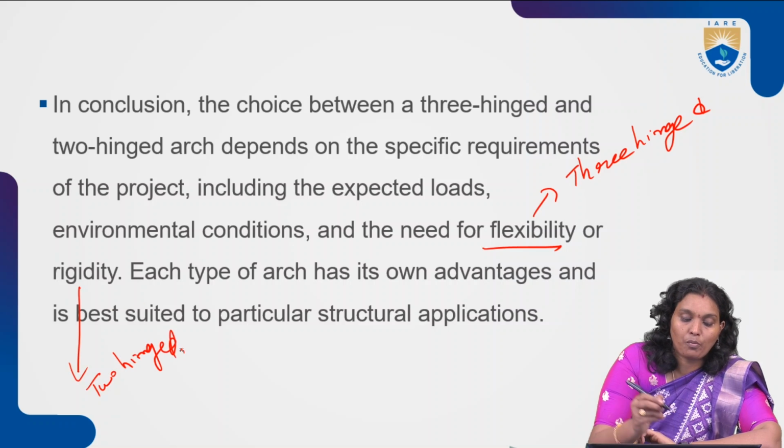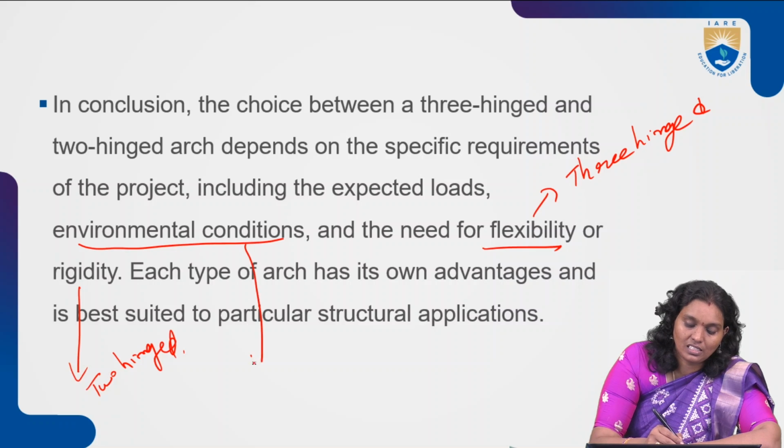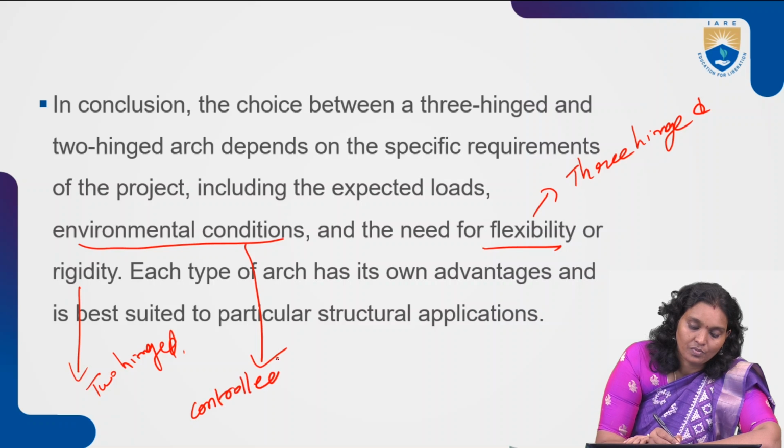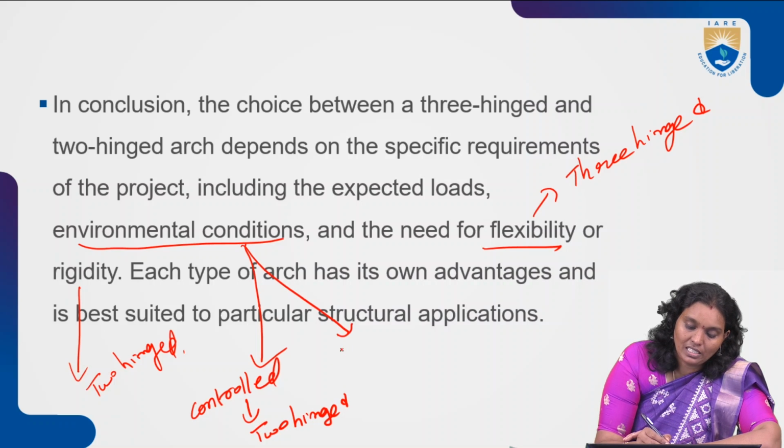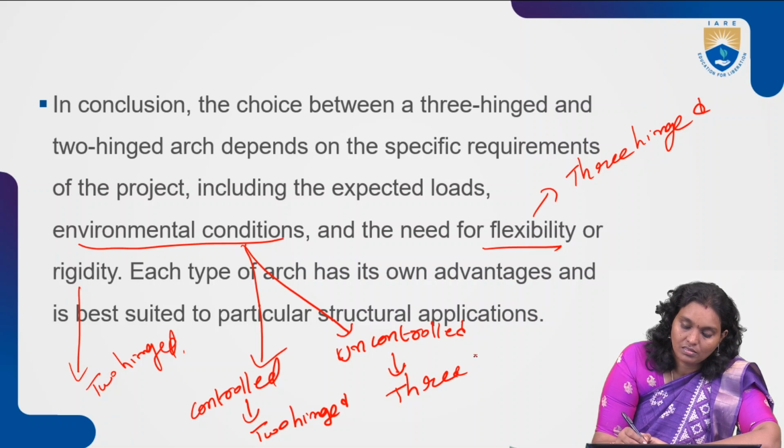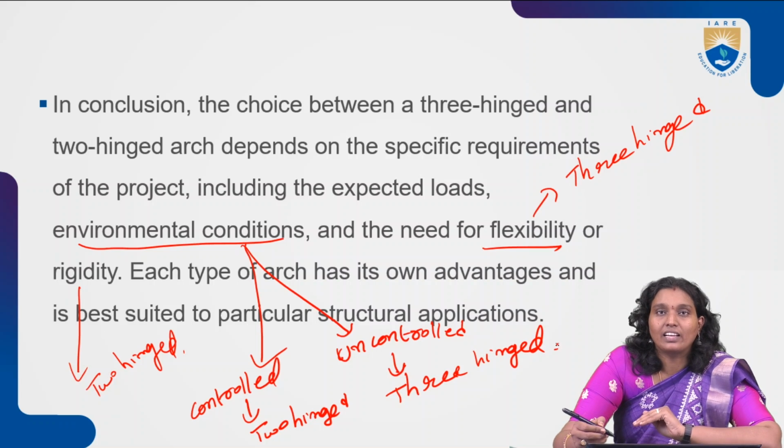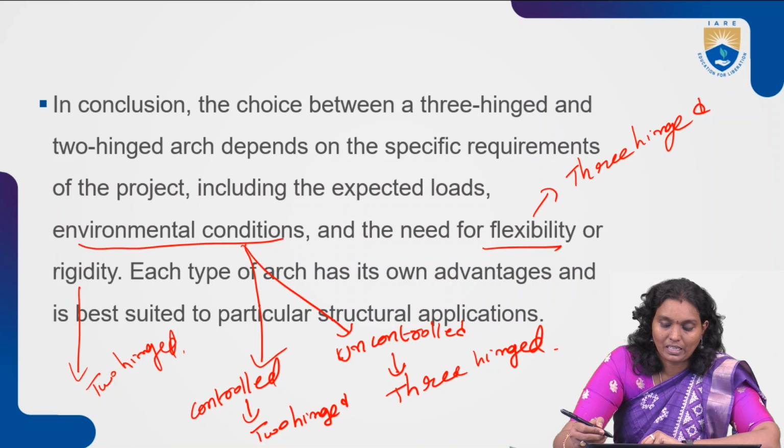From the environmental point of view, for controlled environmental conditions and temperature effects, the two-hinged arch is adaptable. Under uncontrolled scenarios where temperature changes may occur, we may choose three-hinged arches. It depends upon the requirements of the project and the expected load.